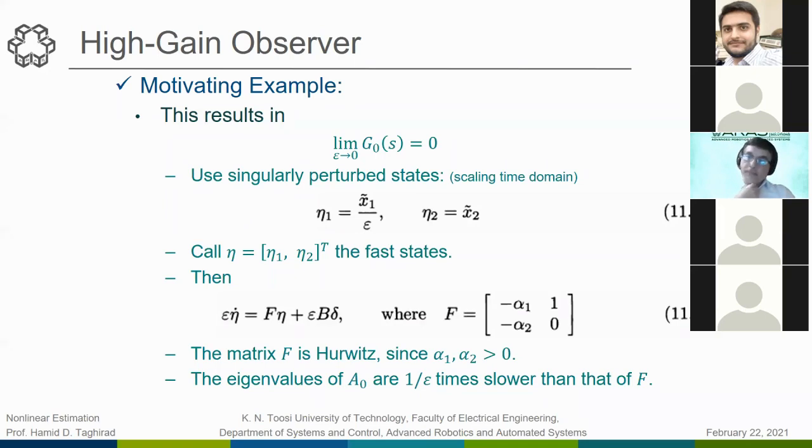When we are using an observer for estimating state values and using them in calculating the controller signal, is it possible that the plant be unstable, exactly like the second state in the last example? Yes, it could be. There is no restriction to always have a stable system in order to observe it.